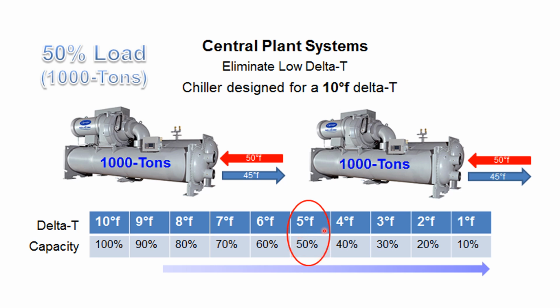If the chiller is functioning at 50% of its capacity, it is becoming more inefficient. A chiller is always better if it is operated at 100%, 90%, 80%, or up to 70% of its operating load, because at that particular time, the specific energy consumption for generating 1 ton of air conditioning is optimum. So kW per TR is much better if the chiller is operating between 100% to 70% of its load. Below 70%, it starts to degrade if it is a normal chiller.